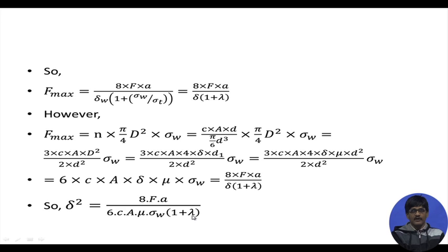That is good. We have now got an expression of delta. You might say, if I give you the machining conditions, can you find out delta for me? Yes. F is known, say F is 10 newtons, E is the magnitude given to be, say, 40 microns, and say C is given, concentration is 0.2, E is given to be a particular cross sectional value, okay, and mu is given, say 1, sigma w is provided for a particular material, lambda is also provided.